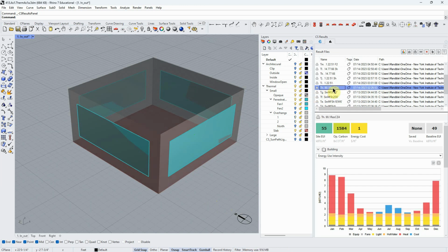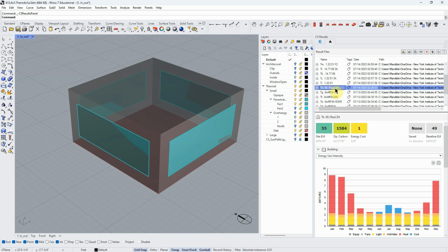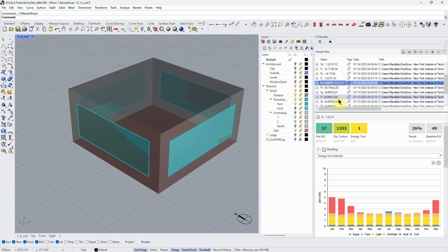So this just shows that there are different ways. This is the other glass that we just had. This is actually the original glass with shading. This is the 90.1 glass without any shading, and this is our new high performance glass without shading. So we're really accomplishing a lot that we were trying to do with physical shading just with the glazing design. But again, this is a pretty high performance, expensive glazing package.